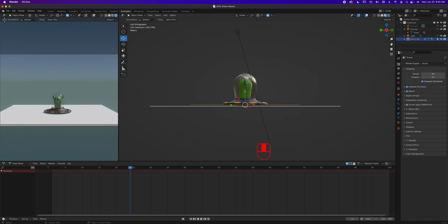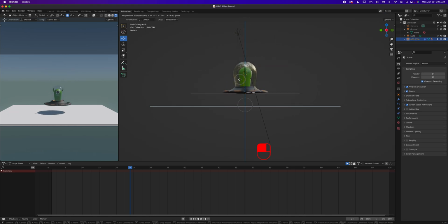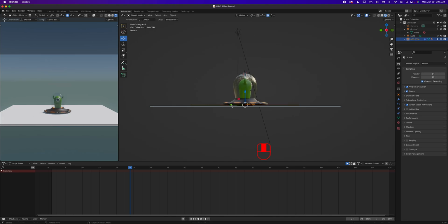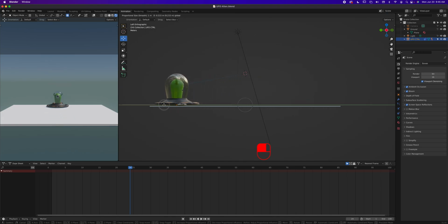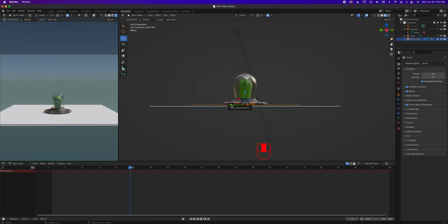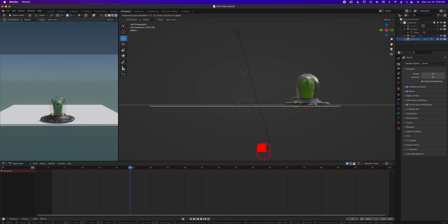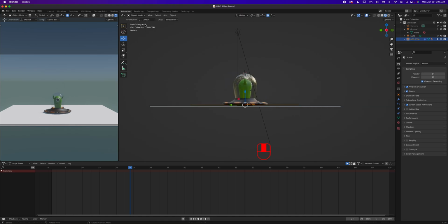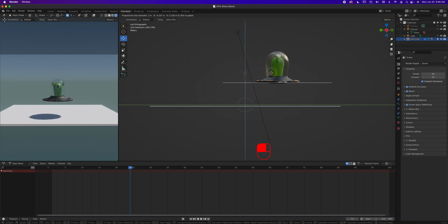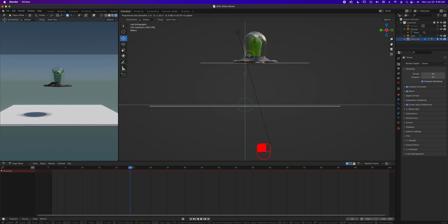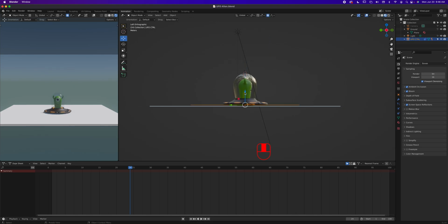Okay, when I go to the left side right here, I see my blue up and down. Right click to cancel. Green, in and out. Again, the green arrow here is not going left and right. It's going in and out because we're on the side viewport here, flat. If I grab the red square, I'm able to move Y and Z at the same time. But for now, we're not going to do that. We're going to go very specific with our movement.